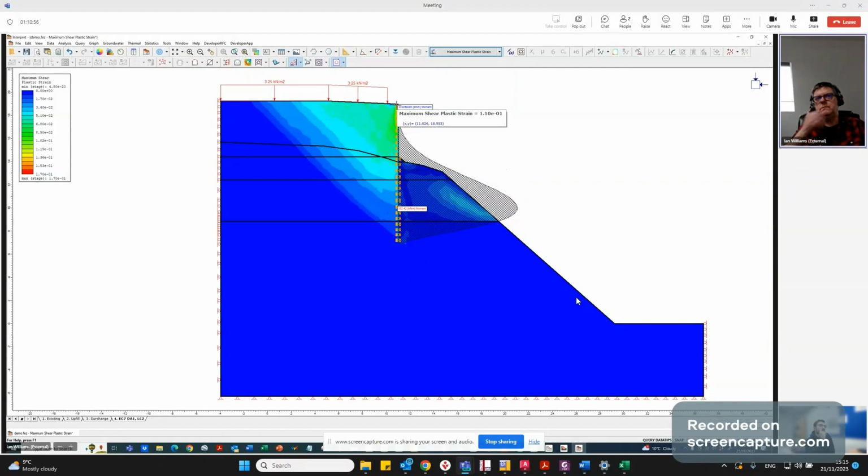You explained to me, but the problems tend not to be massively sensitive to those numbers. The passive resistance can be, but active pressures tend not to be. Your passive resistance does increase as the wall to soil cohesion increases, but that's what happens in reality. You just have to choose a sensible number.